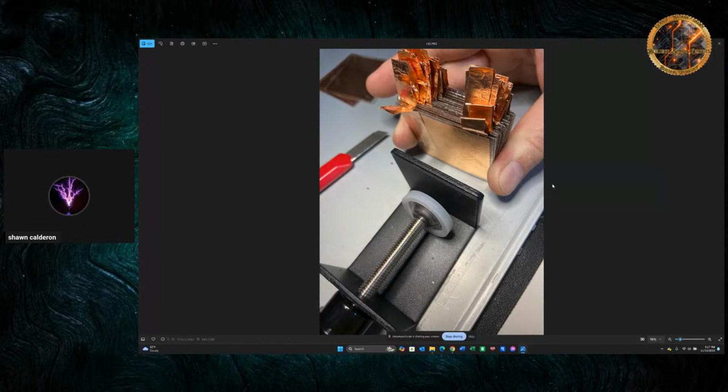The second is that you want the largest plate size, and so the aluminum that I tape to each side of the mica, the bigger those aluminum plates are, the greater the capacitance. And then third, how close you can get those plates together. The closer the plates, the higher the capacitance or the energy storage.